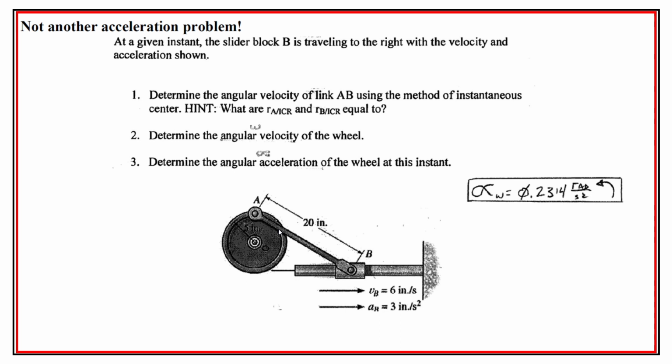It's because it's transitioning from rotating in one direction to rotating in the other direction. So it's just at that inflection point where it's going to have no angular velocity because it has just changed the direction of its angular velocity. So it really simplifies the problem. You don't have a normal acceleration to deal with in the rod. You do have a normal acceleration here, but not in the other one. Yes, ma'am?